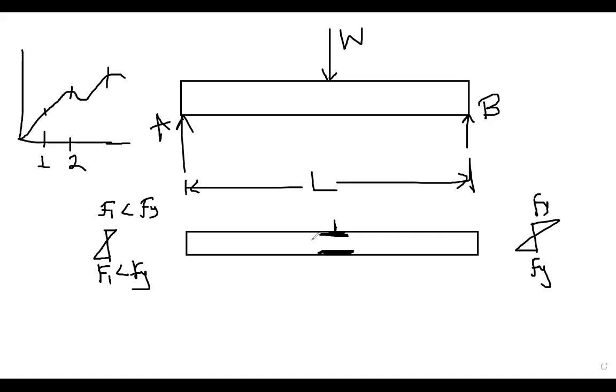So at point 3, the fiber which is adjacent to the extreme fiber is trying to reach the value of its full capacity, that is Fy. And at point 3, in between the ultimate and lower yield point, some fibers are completely yielded, that is Fy, and some fibers are not completely yielded.